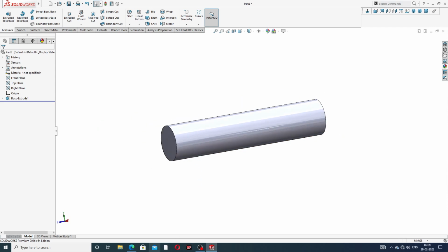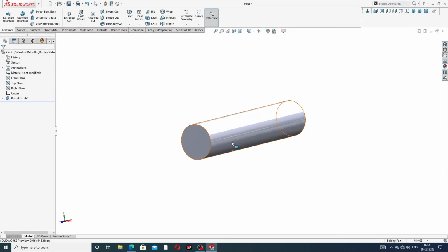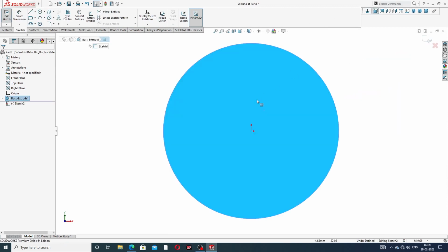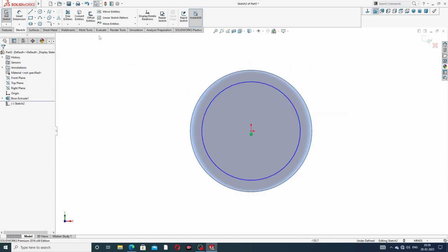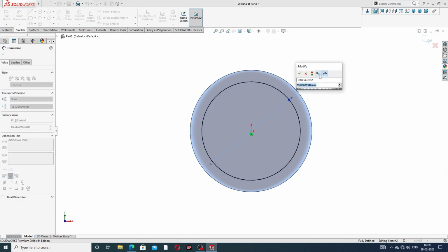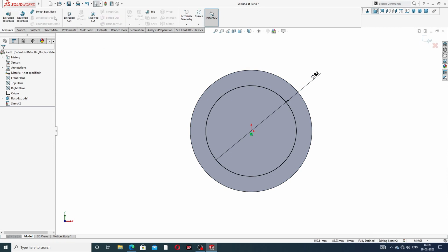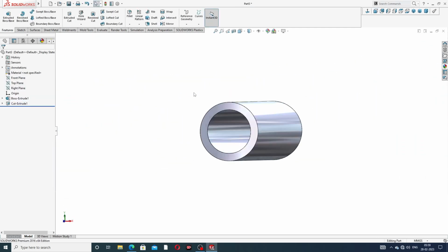And the next point is a cutout, and the cutout diameter is 82, and 82 is the hole. Okay, and at first this face is selected, then sketch normal, and drawing a circle. The circle is this, and 82 dia is cut out. Okay, and extrude cut is this, this is perfect, and okay, this is perfect.